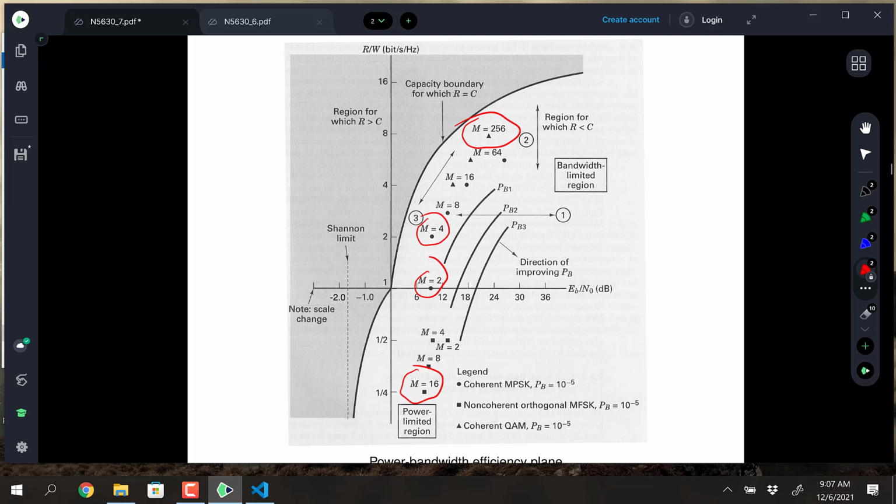It's not great. But now if you add in channel coding, this is without any channel coding, so you haven't put channel coding on this yet. This is just the raw unencoded and decoded over the channel, but this is just how these schemes stack up with respect to information theory and the Shannon limit. So with channel coding, we can push all of those points closer to the limit. Does that make sense? How? Don't know yet, but you can do it.